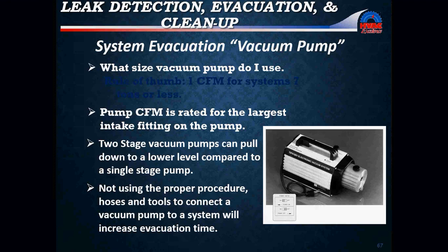Okay? System evacuation, as far as the evacuation pump. What size vacuum pump do I use? Well, a rule of thumb is 1 CFM for systems 7 tons or less.